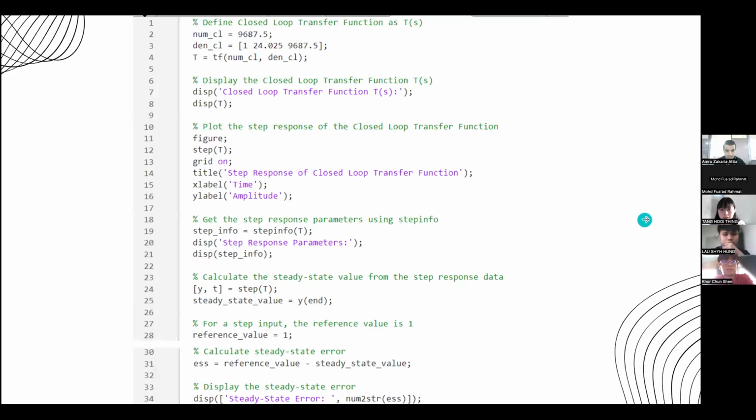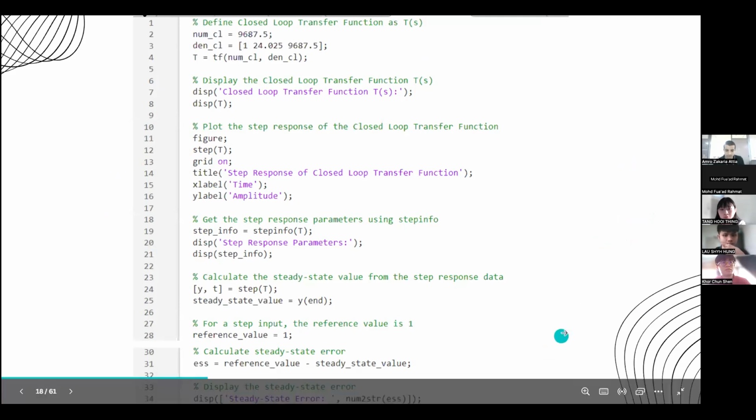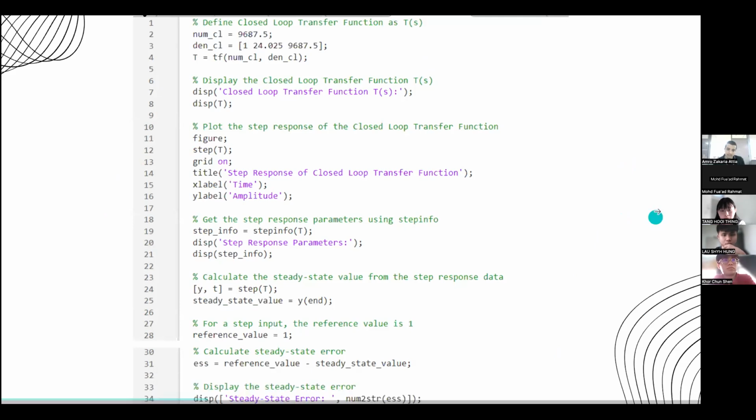For frequency domain analysis in this task, Bode plot analysis is performed for both open loop and closed loop systems. At first, we perform the open loop Bode plot analysis. The values of gain margin and phase margin are obtained from the Bode plot, and both show a positive value. This indicates that the system is stable. To find the range of stability gain, we can use 20 log k equals 69.9 dB, and we calculate the k value. Actually, which slide are you on?